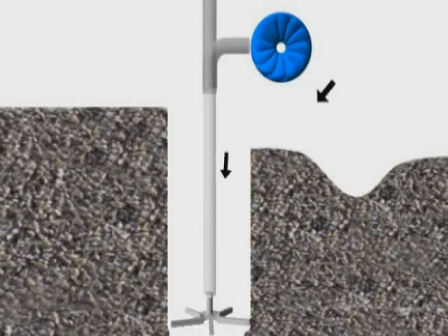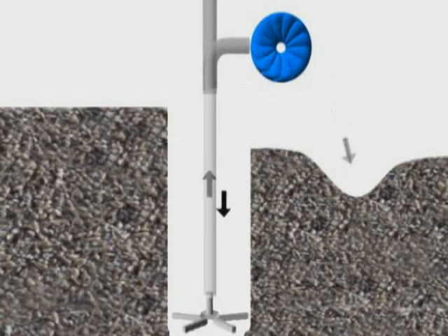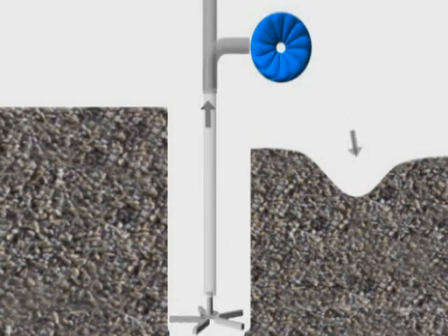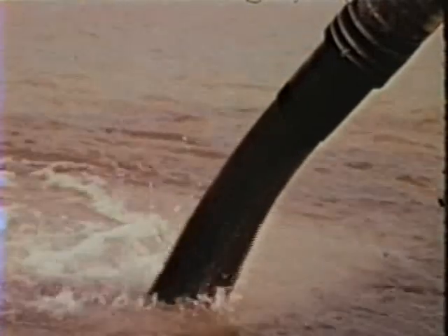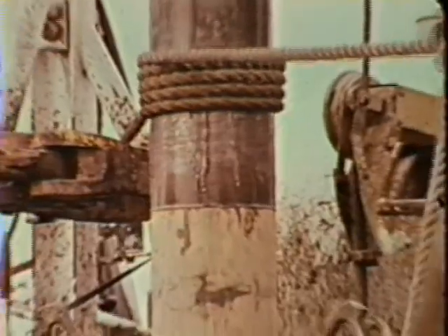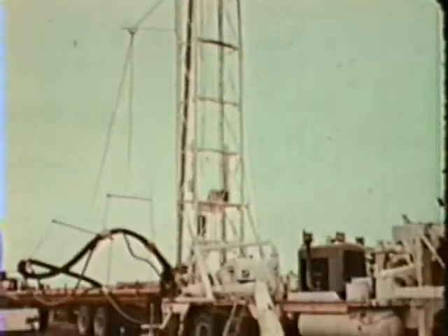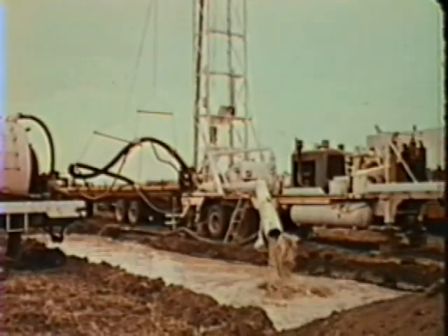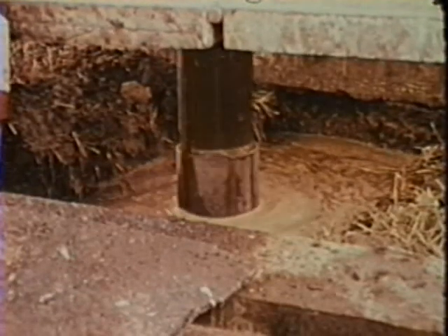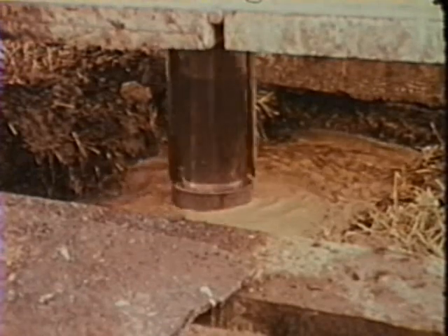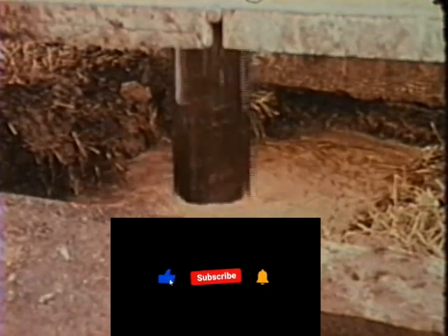The excavated material needs to be replaced with fluid as drilling continues, further increasing the quantity of fluid required for this drilling process. In addition to the makeup fluid required, a significant amount of fluid is displaced and lost in the original formation, as this system does not typically use bentonite and therefore does not entirely seal the hole during drilling. While increasing the demand for liquid used during borehole construction, this system has the advantage of reducing development time as compared to traditional mud rotary drilling.